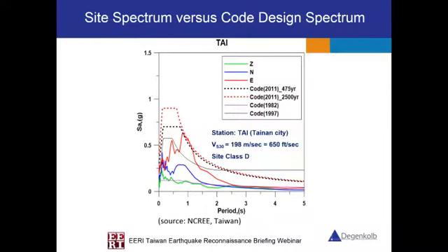Previous speakers have already talked about the ground motion characteristics, and I just want to review that this response spectrum was actually recorded during the earthquake within the Tainan region, which is close to many of the damaged buildings. You can clearly see that the east-west component is higher than the north-south component, and there's a significant peak around a period of about 1 second. At this period, we found 3 damaged buildings. They have a fundamental period very close to 1 second.